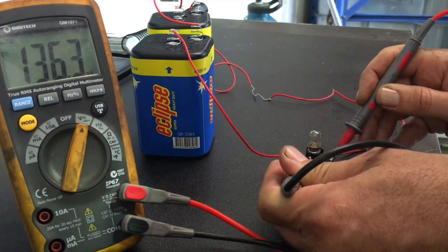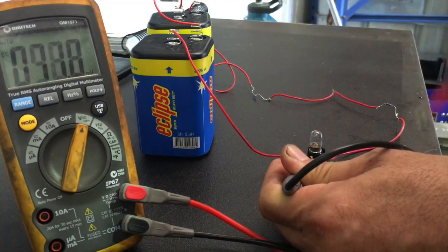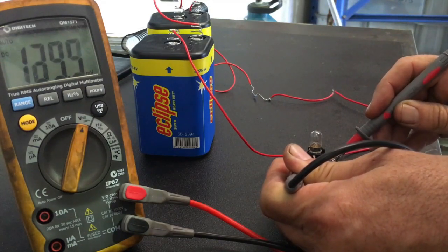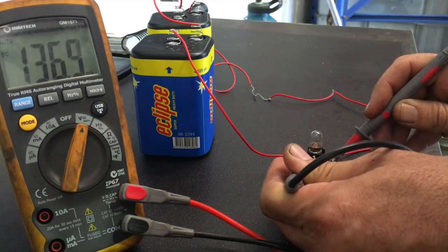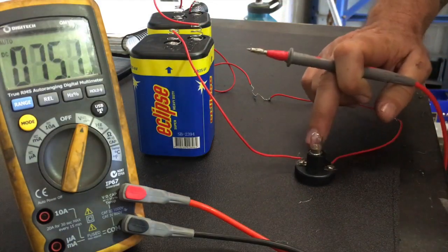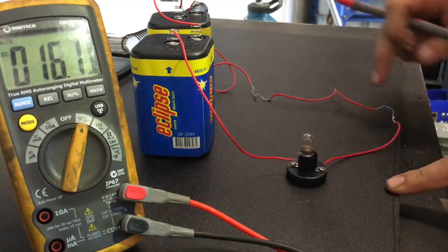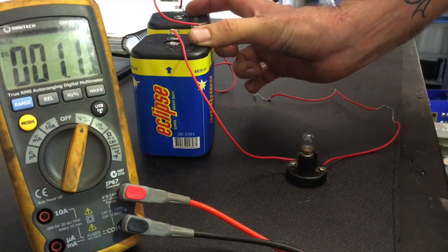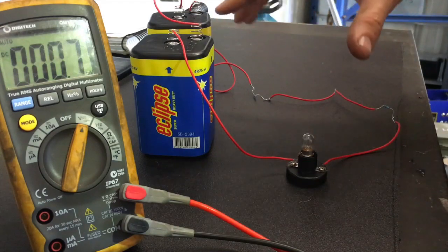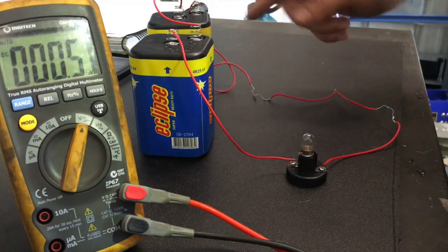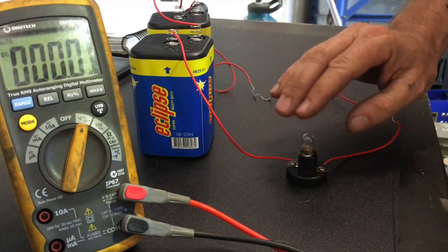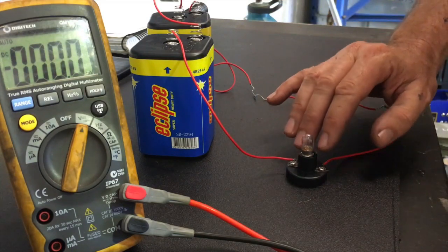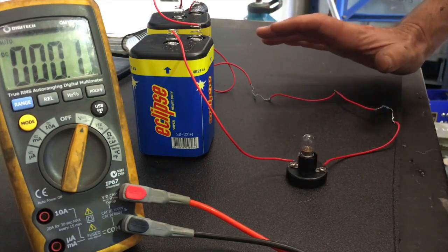So as soon as we measured our voltage across this device, if we were wondering why this globe's not working, as soon as we measured across here, we go, oh, I'm actually getting millivolts. I'm getting almost no voltage dropping here, which means it must be dropping somewhere else, because 12.75 volts is always going to drop on this circuit. If this circuit's connected, the entire battery voltage has to drop along the whole circuit. So if so little of the voltage is dropping over the actual light that I want to run, it's got to be going somewhere else.